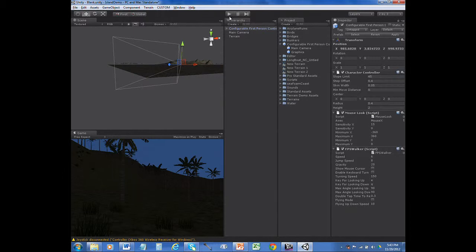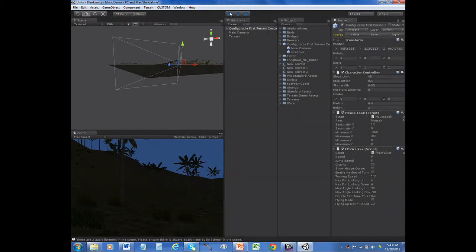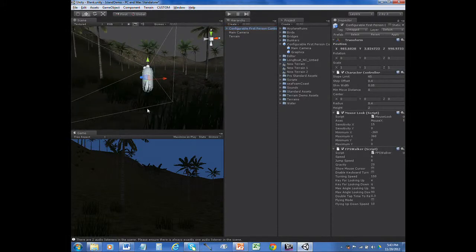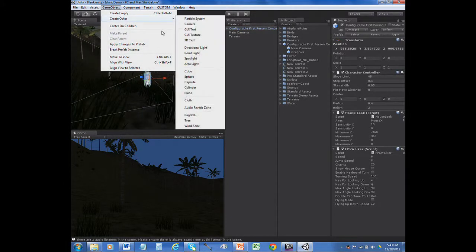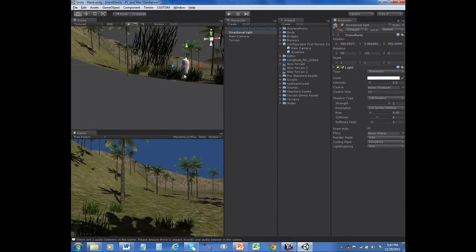So anyway, right now, it doesn't look that overwhelming, but it's very, very hard to see. So what I'm going to do is I'm going to have light coming in. So let me put a little sunlight so you can see exactly what I'm talking about. So I'm going to do a directional light. So now, can you see? That light, again, only one. Directional light represents the sun. And again, you could do this in Max, embedded into the geometry, but I'm doing it here. So check this out. I'm going to go and add a little shadow. So now I can see my texture.